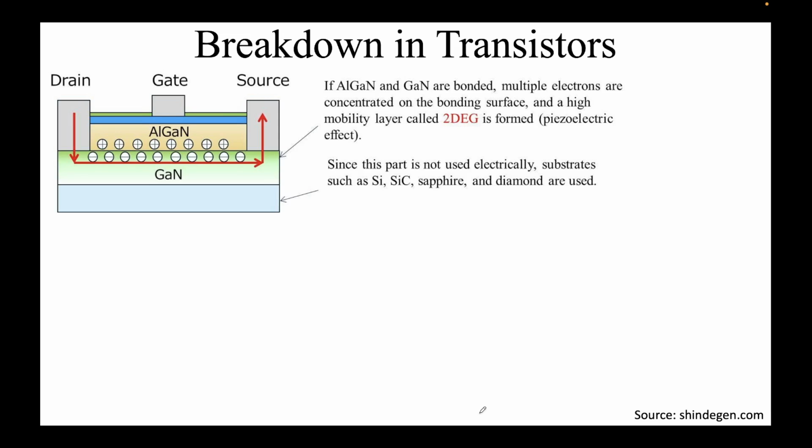So how much are we deviating from those ideal concepts that we had talked about, right? The first of them is something called the breakdown characteristics. We already know in a PN junction, I already explained in the summary, avalanche breakdown. Essentially, the current is supposed to be very low, or ideally 0, but let's say some very low amount of current, nanoamps. But all of a sudden, the current does not stay at nanoamps, it increases. That is effectively what we call the breakdown. And that usually happens when the device is in the off state. In the on state, it is supposed to conduct current.